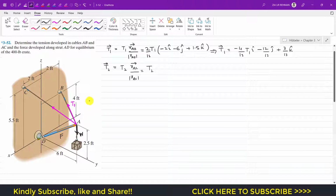So to reach that point C, again we need to move along the y axis first. So we need to move from here to here, that is parallel to the y axis, and this distance is again 6 feet. So we need to move 6 feet in the negative j. So we will write minus 6j,